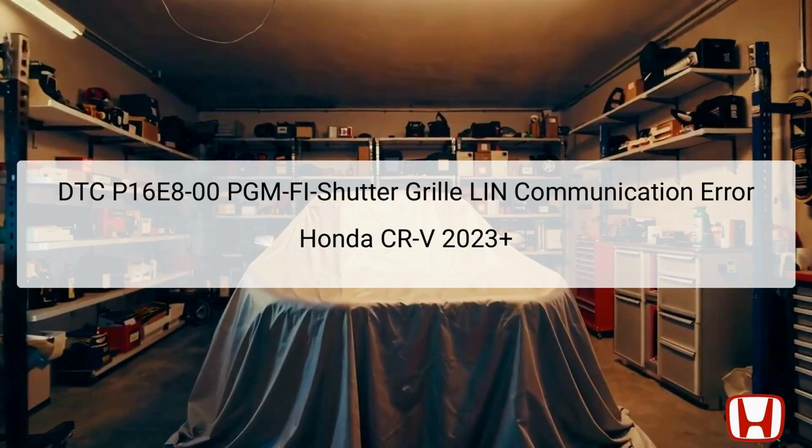The DTC P16E8-00 indicates a communication error within the Linear Communication Network, LIN, related to the shutter grille in the Honda CR-V 2023 model onwards. This error occurs when the powertrain control module, PCM, is unable to receive necessary signals from the shutter grille via the LIN.